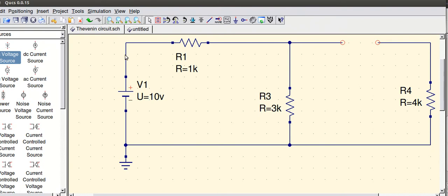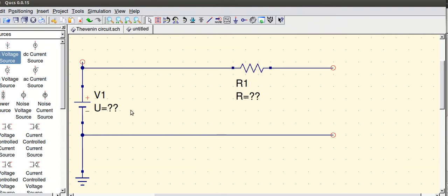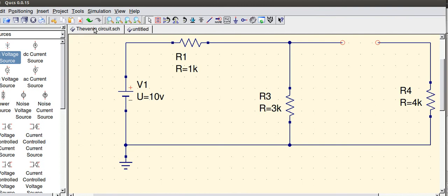Alrighty, I went ahead and drew one. A Thevenin circuit is that voltage source and that resistor in series. So if I put in my voltage source here, 7.5, enter, and my resistance here, 4750, enter. Now that is my equivalent Thevenin circuit for that.